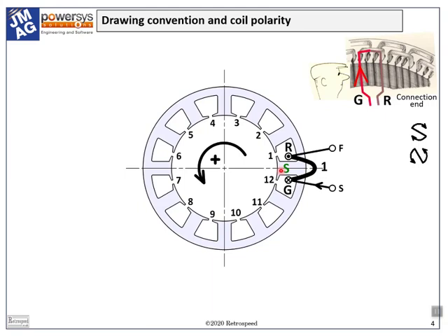Note that when we have a south magnetic pole between the conductors, the rest of the bore takes up a north magnetic polarity because the flux must go in closed loops. Since the area of the rest of the bore is much bigger, the flux density is much smaller in the outer regions. This is an example of Gauss's law. We'll see this formulated more precisely later. The diagram represents the direction of winding the coils.